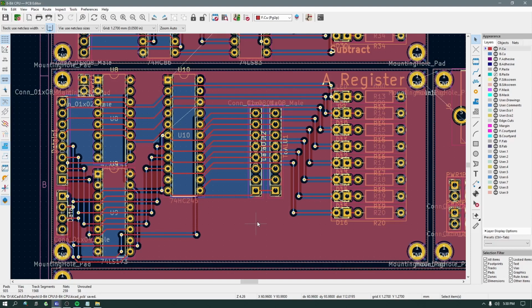The chip on the right is a tri-state buffer chip. This chip is used to control the flow of data going in and out. It's called a tri-state chip because it can be in 3 modes: inputting data, outputting data, and blocking data both ways. The headers on the right are data out and data to the ALU. The LEDs also show the contents of the register. The headers on the left are for power, data, and the read, write, and clear signals.